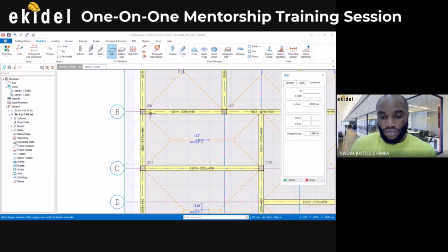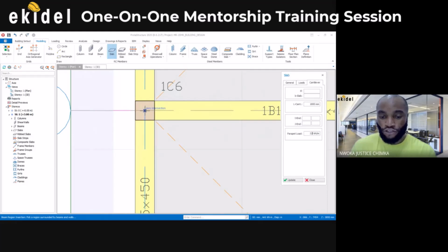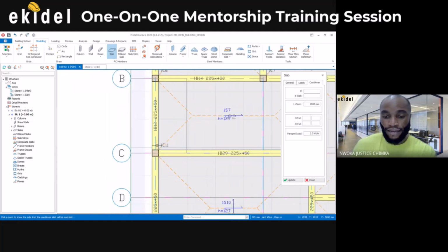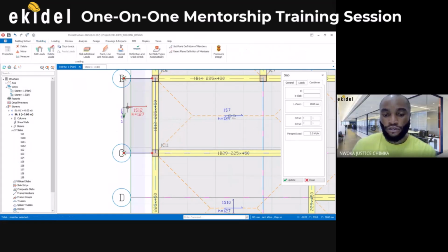Once you define your load and your cantilever length, to add the cantilever, you just click on the point where it starts from. Let me say it starts from here, and then the last point. I'll click on this place, and then you can see it asks you to specify either in or out. In this case, we are out. I'll click on out here. You can see the cantilever here.